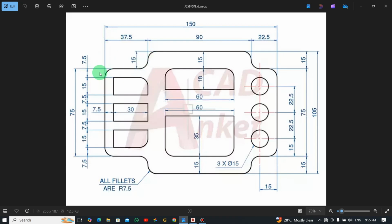Now let's come to the inner side. The gap between this space is shown here, 7.5 mm, and then from this side to this end is 15, and this is also 15. So repeated: 7.5, 15, 7.5, 15. Okay, so let's open our AutoCAD and start from this place.